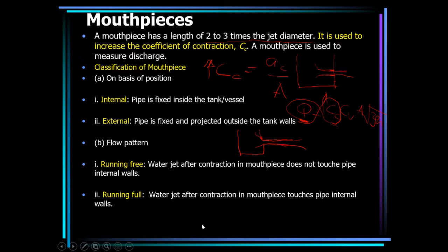I will correct the typo on the slide. And the other one, running full, is when the water jet after contraction in the mouthpiece touches the pipe internal walls.